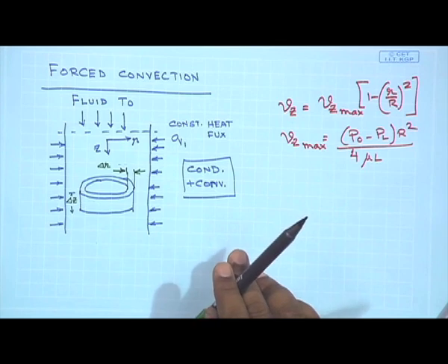So, see the problem that we are facing right now. So far we were visualizing only one smaller dimension and making a heat balance, but now since the temperature is a function both of R and Z, the shell across which all heat entry are to be balanced has two smaller dimensions, one is delta Z, the other is delta R, and through the top surface, through the annular top surface, which has an area equal to 2 pi r delta R, you are going to have convective flow due to the motion of the fluid as well as conductive flow since the temperature varies with the axial position.